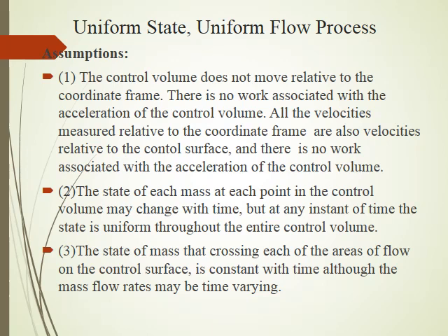However, while we are analyzing unsteady flow processes, we should be careful about the mass and energy contents of the control volume as well as the energy interactions across the boundary. Some of the common examples of unsteady flow processes are charging of rigid vessels from supply lines, discharging a fluid from a pressurized vessel, driving a gas turbine with pressurized air stored in a large container, inflation of tires, and even cooking with an ordinary pressure cooker.